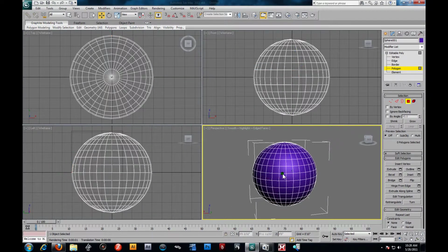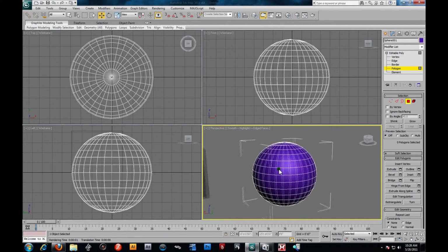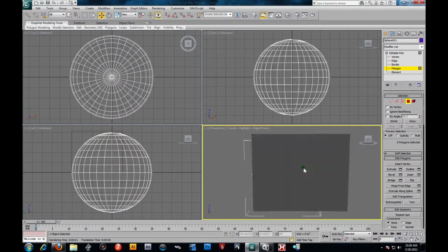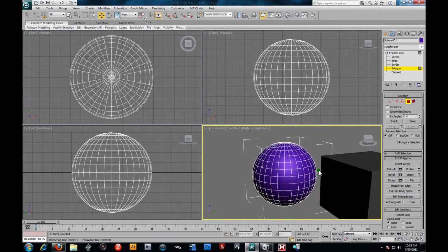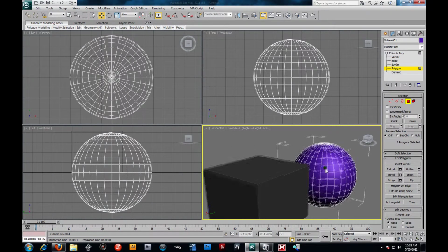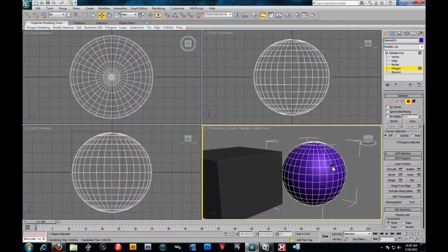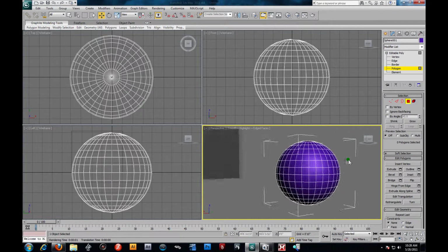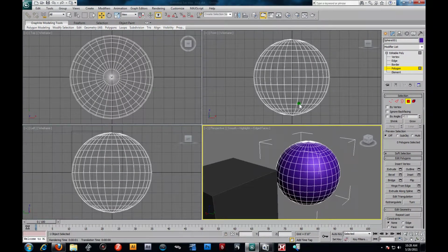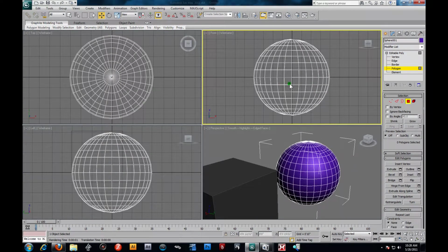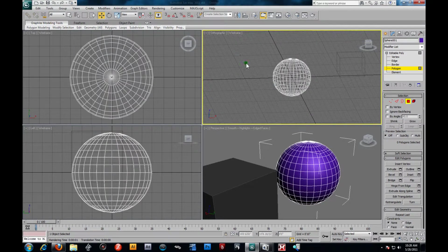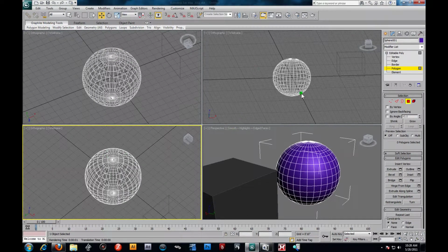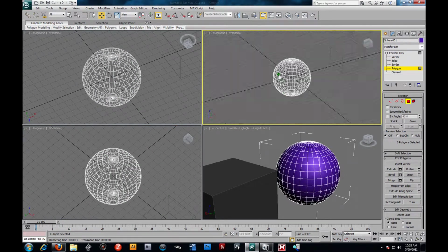Alright, so that's pretty much your basics on your viewport. I'm sure we can get into a lot more. But as you're starting out and modeling things, things will start to catch on. You'll start to pick up some pretty good habits. Usually in my videos, what I like to explain is things that you don't want to do, bad habits you don't want to create. For example, one of the most important things about this video is if you accidentally get in orthographic. Notice I'm in orthographic in all my viewports. I highly recommend not trying to work in this view because this can really screw you up.